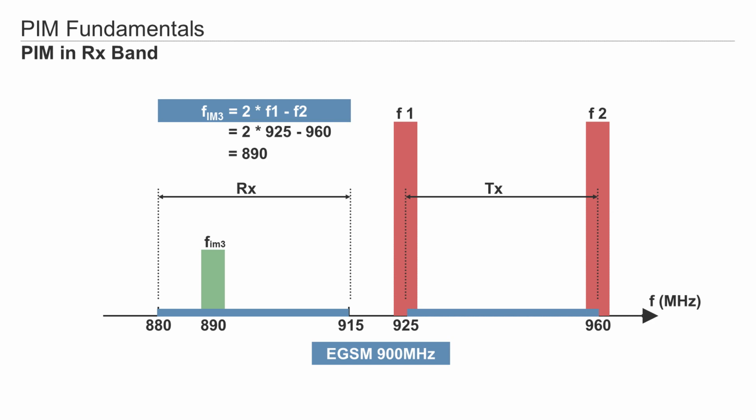The power that a mobile device can send out to the base station is limited. Therefore, if noise is created in a transmission line because of PIM, the BTS can no longer understand the mobile devices so well. It can happen that the contact is interrupted or even gets lost completely. You will recognize this in bad coverage, bad connectivity, and slow or no data transmission. In this example, PIM is based on just 2 TX frequencies.